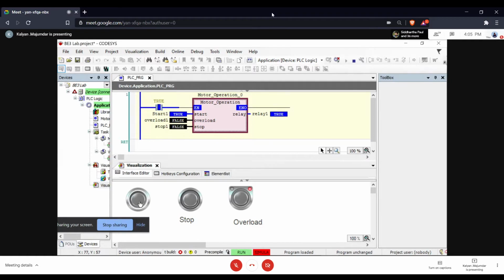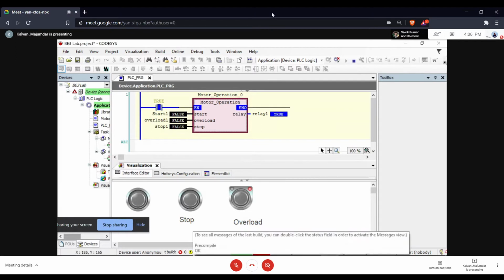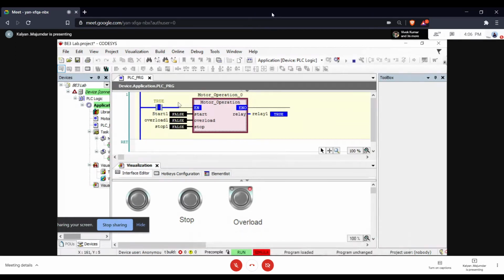Here, if I press start, see here, this becomes true. Start 1 is true. That means this particular switch is linked with this variable, just what we did a little while ago. So your motor has started. Press stop, this becomes true, so your motor turns off. Again started, the motor is running. There's a push button. See, if I click it, it becomes on. I release it, it immediately becomes off, but the motor is latched to the on state.